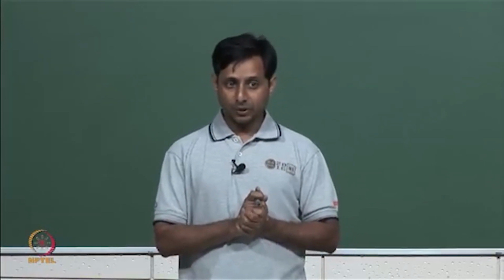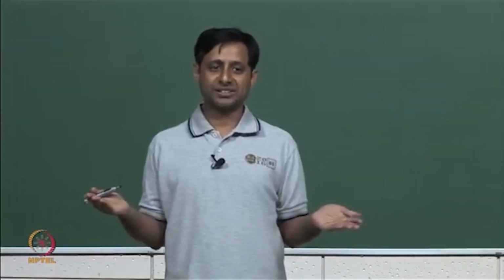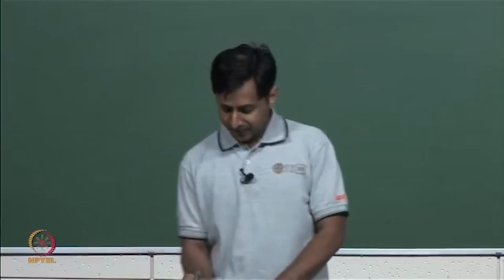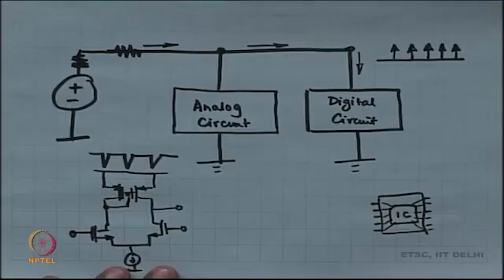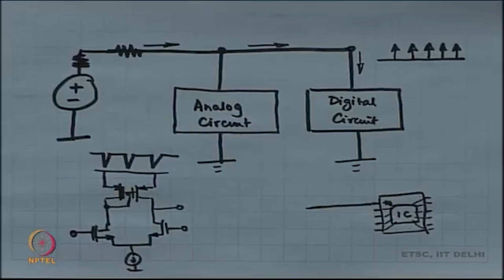25 micrometers could be the diameter of that gold wire, right. So, if you have a thin wire, what is it going to present? It is going to present inductance. So, these wires present inductance. Then this power supply wire, which is inductive already. So, this is already an inductor that goes through a long wire, which is again not very thick, right, all the way to the power supply. That is also inductance, right.